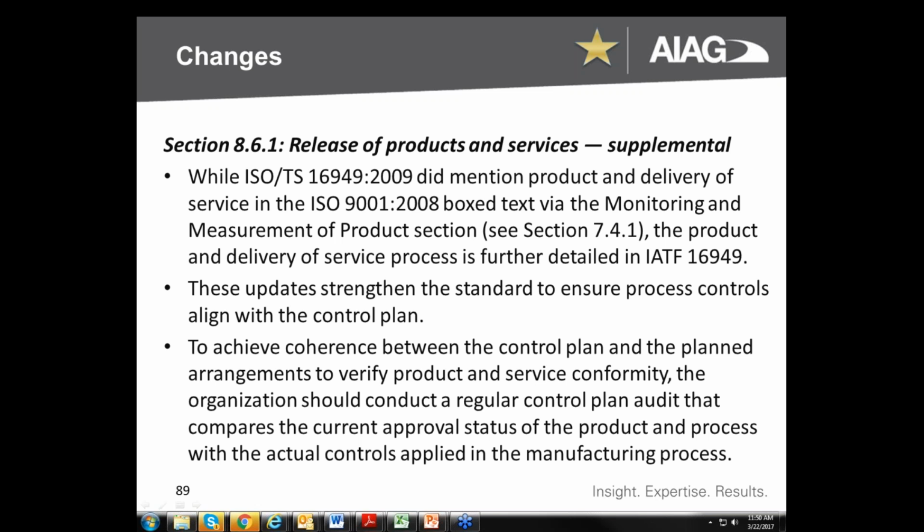The new standard does not make exceptions for small supplier designations, Lisa. Robert, 8.5.6.1.1, the last section I talked about today, yes, you have to have a backup for everything. Let me go back to that particular section. 8.5.6.1.1: Maintain a list of the process controls, including inspection, measuring, test, and error-proofing devices. You need to include the primary process control and the approved backup or alternate method. This means everything on your control plan.